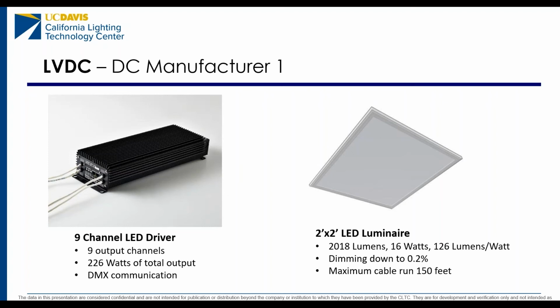When we specified each DC system, we wanted to maximize the load that we could put on the power supply. So we picked luminaires with the highest rated wattage that we could find. And secondly, in terms of system architecture, this LVDC system is the most basic of the DC systems that we looked at, in that it's essentially one centralized driver for 9 luminaires, and that's pretty much it.